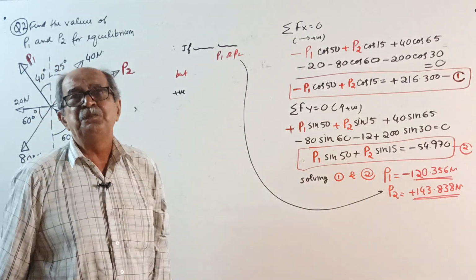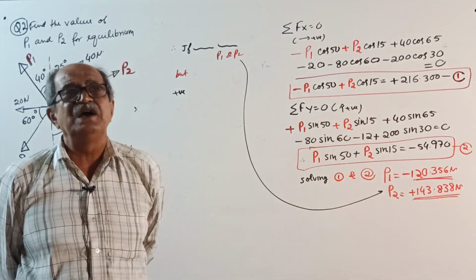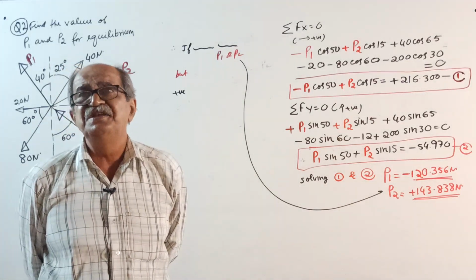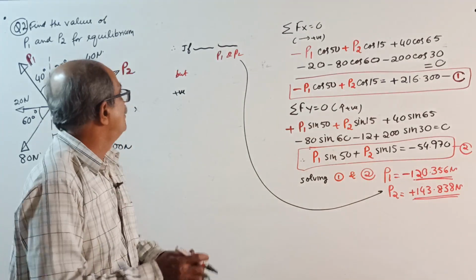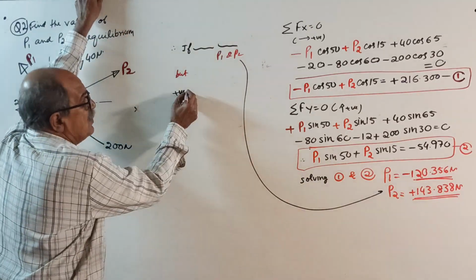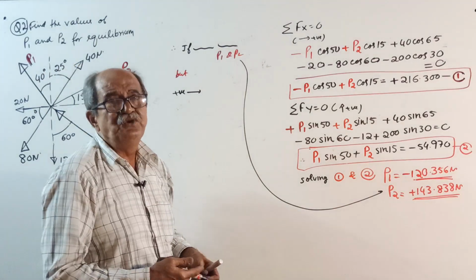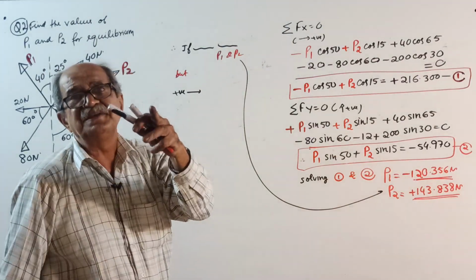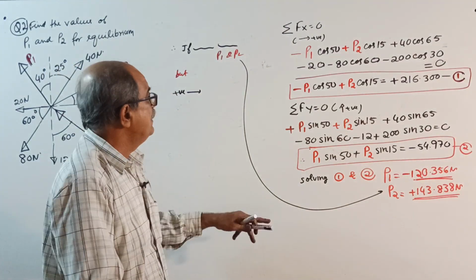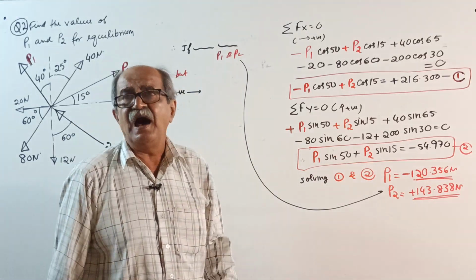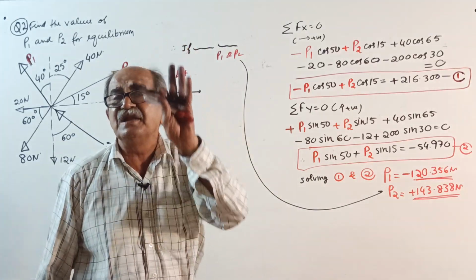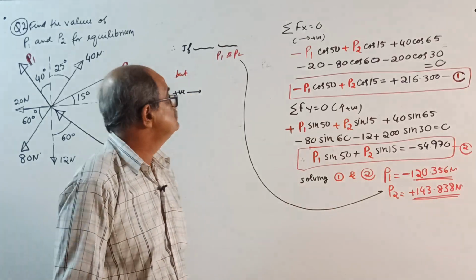Complete confusion remains for sign convention in structural engineering, not now, little later. If you get a positive sign for the unknown, it means the assumed direction or given direction is correct. Therefore, that unknown is in the same direction, with that value.